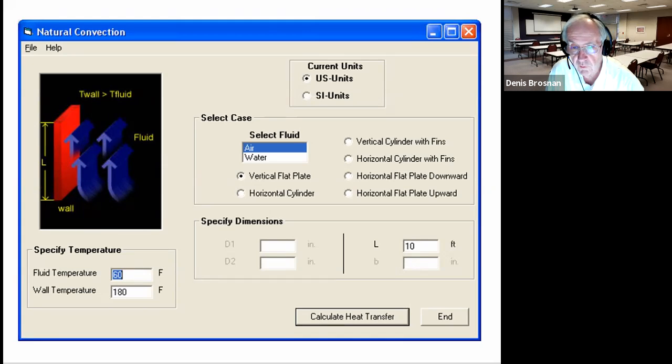It's pretty neat. Given those conditions and the temperatures I've chosen in this particular example, which look like 60 degrees Fahrenheit and a wall temperature of 180 degrees Fahrenheit, remember that you want that wall temperature always to be low enough that you don't scald a human being's flesh if they touch the side of the furnace. Otherwise, you need to protect the furnace, put it in a cage or something so somebody can't touch it.